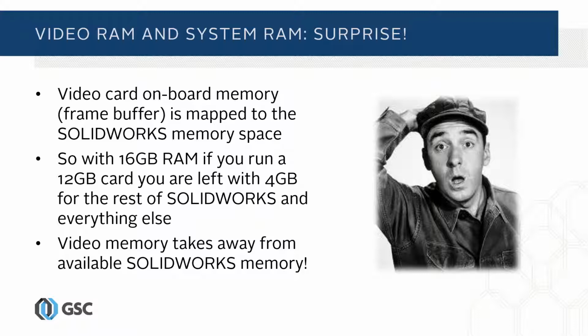This manifests most often when someone takes an older computer, goes out and buys a higher end graphics card, sticks it in that older computer, and then when they're running SolidWorks, they immediately start getting all kinds of "you're low on resources" messages, because this is what's happening. So the moral of the story is you scale the entire computer.